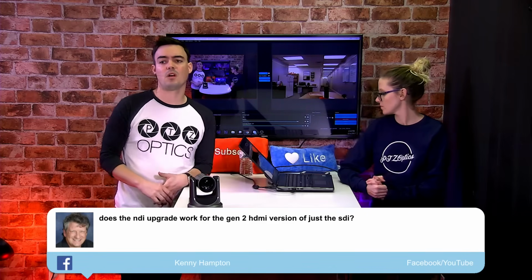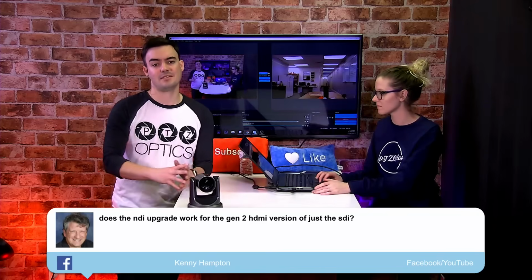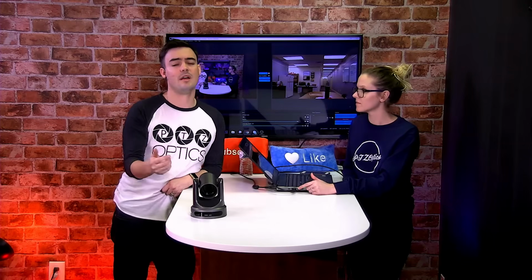Kenny's asking if the NDI upgrade will work on the Gen 2 HDMI version. There is no HDMI version. All the PTZOptics cameras have HDMI with the exception of the Z cams. So all of our cameras, even the SDI and the USB, all have HDMI. The difference is there's one with a USB port and one with an SDI port. The SDI ones will get the first update on the NDI, because those are the ones that really have the PoE and the need for it. But yes, the USB models will have an NDI firmware update, and so will the Z-cams eventually, hopefully early 2018. And nothing will be taken away with the NDI cameras, which is important. Except for the fact that you won't be able to use RTSP, because that's essentially what the NDI HX is using.